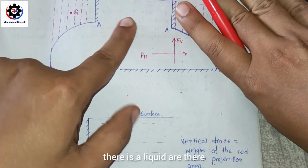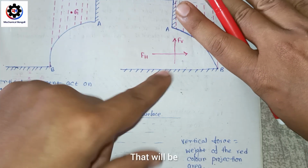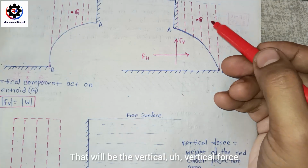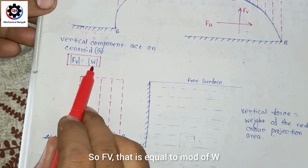So on the left side there is a liquid. This is the free surface. This is the liquid. Okay, so what will be the vertical force? That will be from here to here. So this is the red color projected area, and that will be the vertical force. The vertical component acts on the centroid G. So Fv is equal to mod of W.